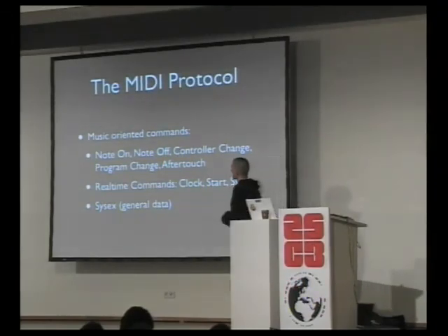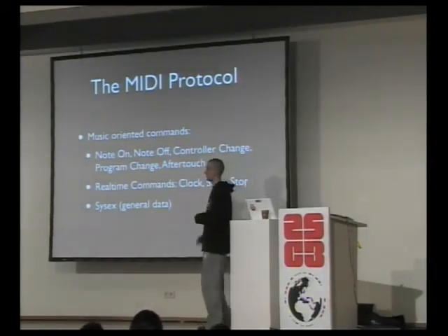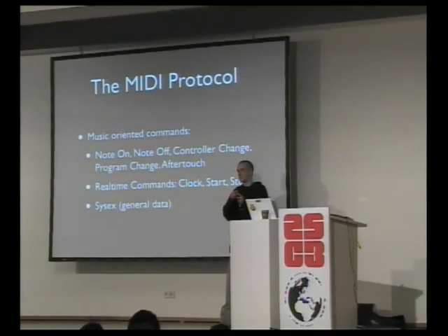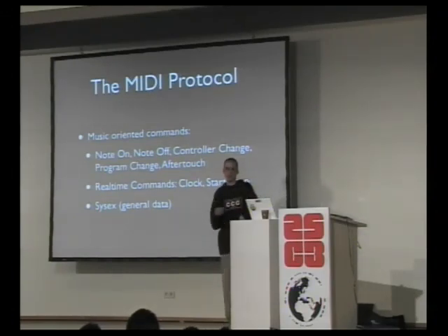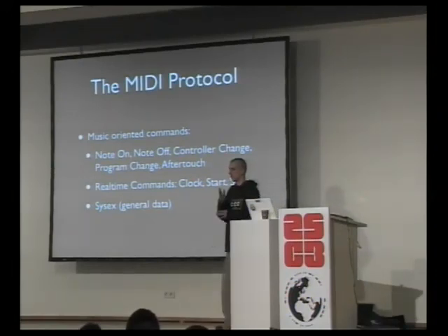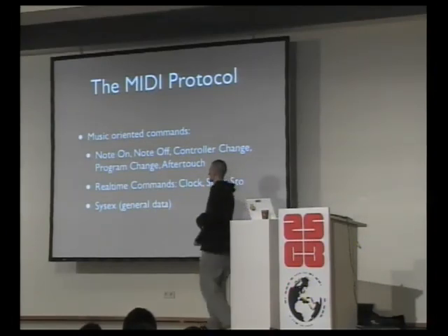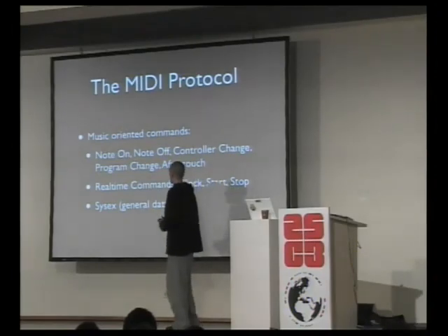But then you have real-time commands, which are called real-time because they have a high priority. So it's clock messages, for example. If you have something called a sequencer, which is basically just a program that sends back stored information, it has to be synchronized to, for example, another sequencer, so that they don't start to play out of phase, out of rhythm. So it sends a lot of these clock messages regularly on the MIDI cable, and it's used to synchronize sequencers. You have start and stop messages,